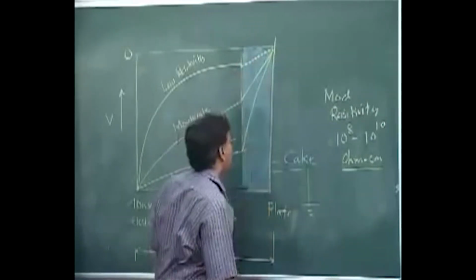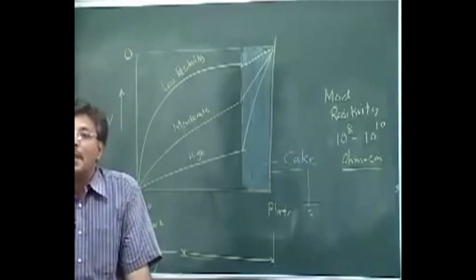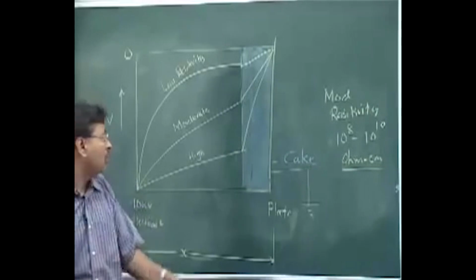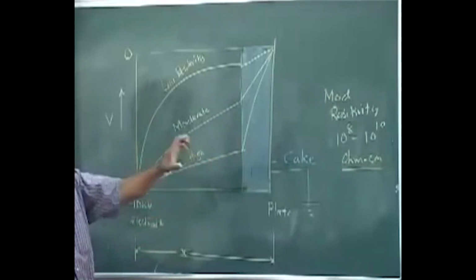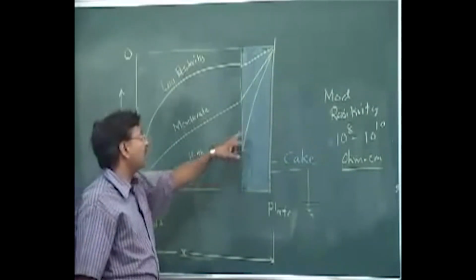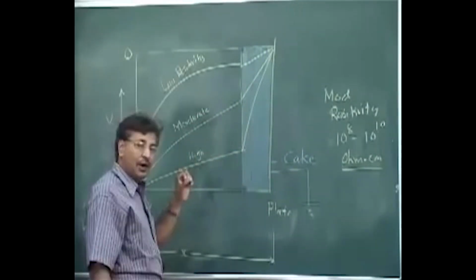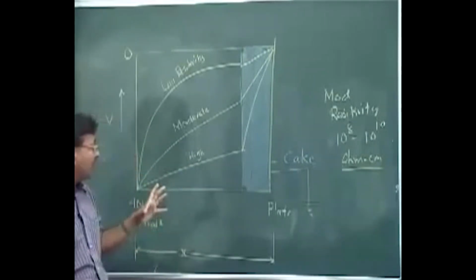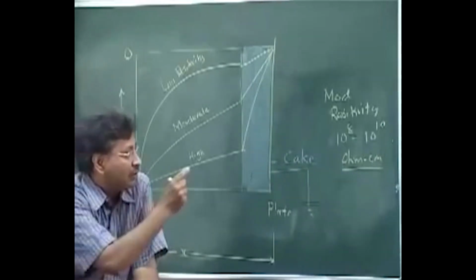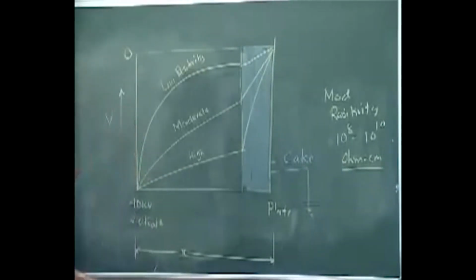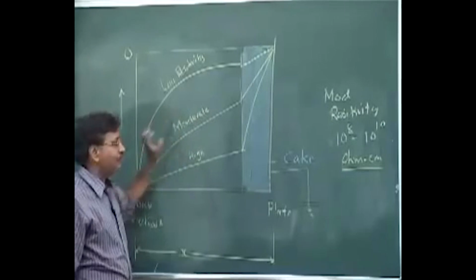Because of this voltage difference, there is a possibility of generating back corona, because of the huge difference you see here and here. The corona we developed at the discharge electrode, that phenomenon can occur here, and if that occurs, there is a fear that the particles will not only dislodge themselves, but there is another fear that it can catch fire. So the ESPs work best under moderate conditions.